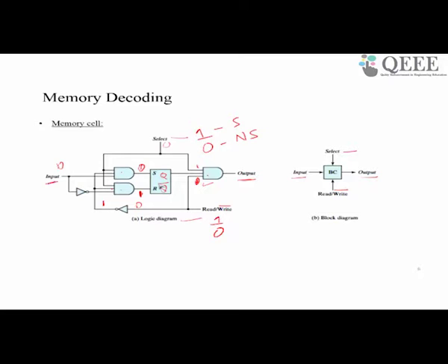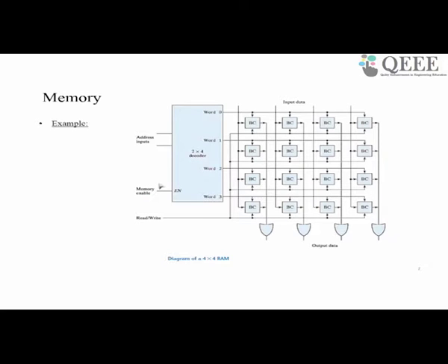So this bit cell can be used to write a bit into a cell or read from it, and we can have the option of selecting it or not selecting it. Now we can put a group of these bit cells to construct a register and a group of registers to construct a memory. As a simple example, we will see how a memory of 4 address locations, each storing 4 bits, can be constructed. So we will have an array of 4 by 4 bit cells as shown here, and we need a mechanism to select.